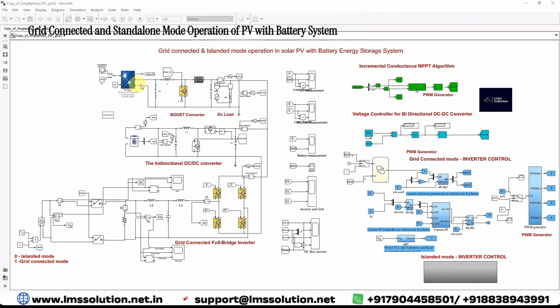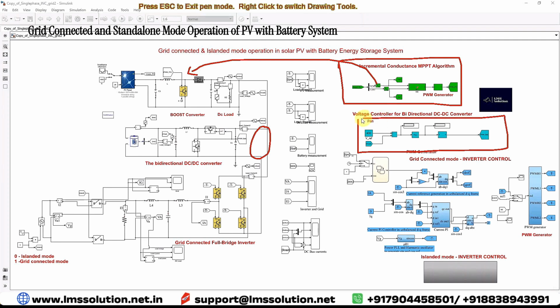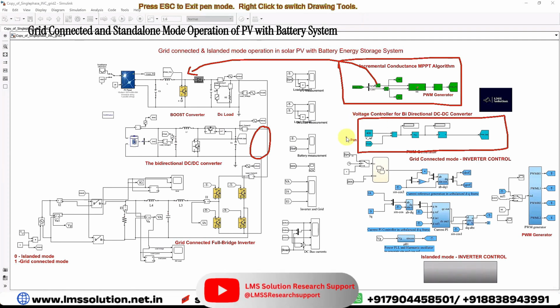The PV panel is controlled by means of incremental conductance MPPT. This incremental conductance MPPT is implemented here for the solar PV system to extract the maximum power from the PV panel. And the output voltage of this bidirectional DC-DC converter is controlled by means of a voltage controller. Here we used a PI controller to maintain the DC bus voltage at 400 volts. And then this inverter can be operated bidirectionally when it is connected with the grid system.